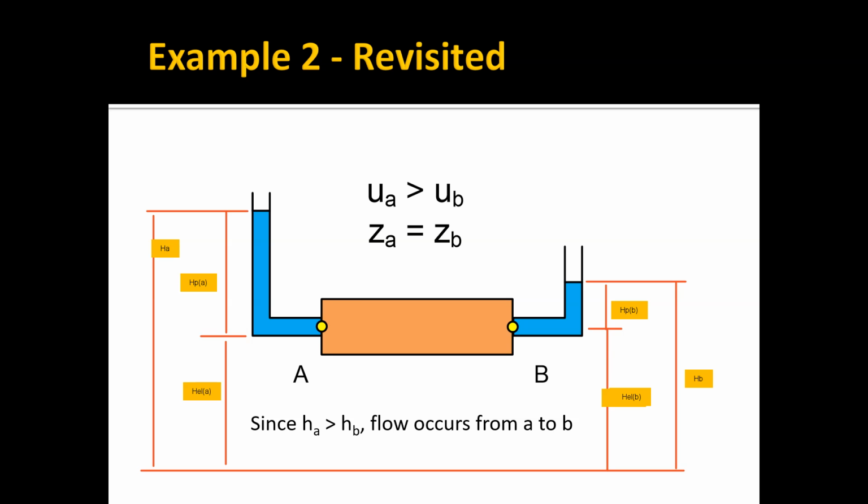So this is a principle that's really important in groundwater modeling and understanding flow in aquifers. The total head, another way to think of that is the water table, measured relative to a datum, which is typically sea level. So water is always going to flow from where the water table is high to where the water table is low. That's a really simplistic way of viewing it. And it flows in the direction of the maximum downward gradient.